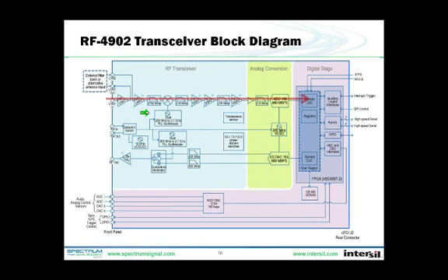The receiver does a single down conversion of the signal in the analog domain with the high IF architecture. We use the high linearity analog stage for a high instantaneous dynamic range to ensure that the analog front end is not saturated before the signals even get to the ADC. In addition to high instantaneous dynamic range, there's a wide range of receiver gain adjustment. This enables automatic gain control to provide the ADC with signal levels close to their optimal levels. It has an ultra-low jitter clock generation circuit close to the ADC and DAC, and this is critical when you're operating with high frequencies entering your ADC.